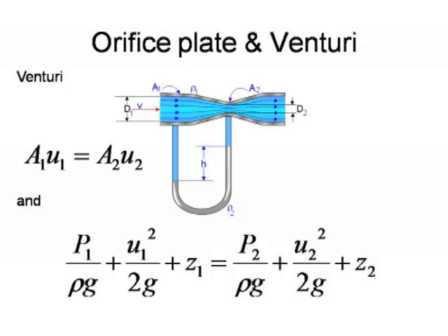And then the equation at the bottom there is Bernoulli's equation in terms of energy per unit weight, because we've divided through by g. In fact, that equates to simply measuring terms in terms of their head. So we have the first term is the pressure head, the second term is the velocity head, clearly fairly similar to half mv squared, or half times velocity squared. The third term on the left is the height above the datum, and then on the right hand side we have again the pressure head, the velocity head, and then the potential head.